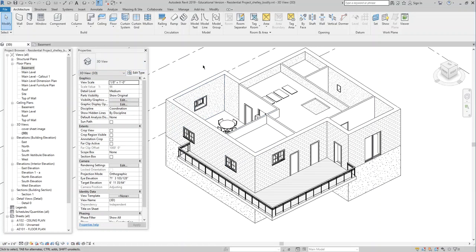Make sure that you have your basement level defined. Make sure that when you're finished, if you know the foundation isn't completely aligned to the upper walls, you go back and align it, right? The nice thing again about Revit is that even if you don't generate those walls exactly correct the first time, meaning there's some slight misalignment, you always have the ability to go back and fix it, right?